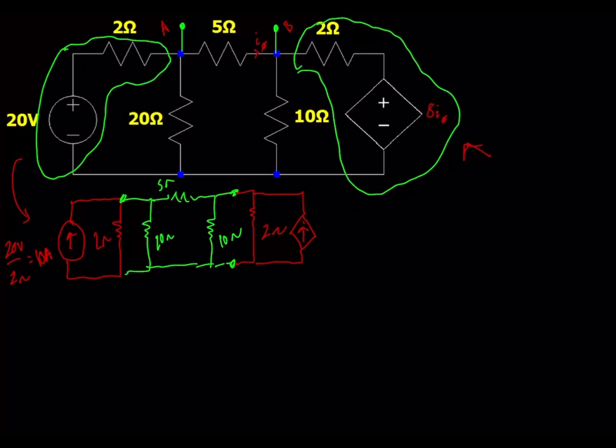So again, this dependent current source will be its original value divided by the resistance, this 2 ohm resistor, and that gives us our new value, which is 4 I naught. And if we remember, this is I naught as defined. So we're just using source transformation, changing these voltage sources that are in series with their resistors and giving them an equivalent circuit of current sources in parallel.